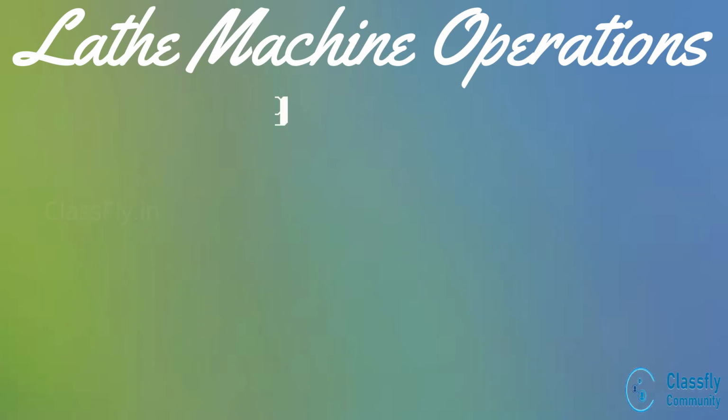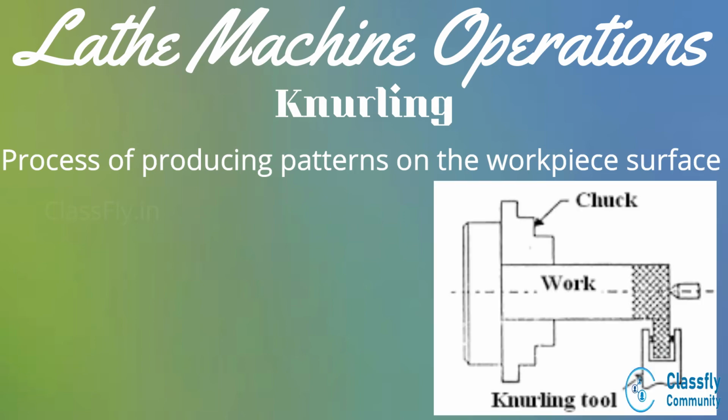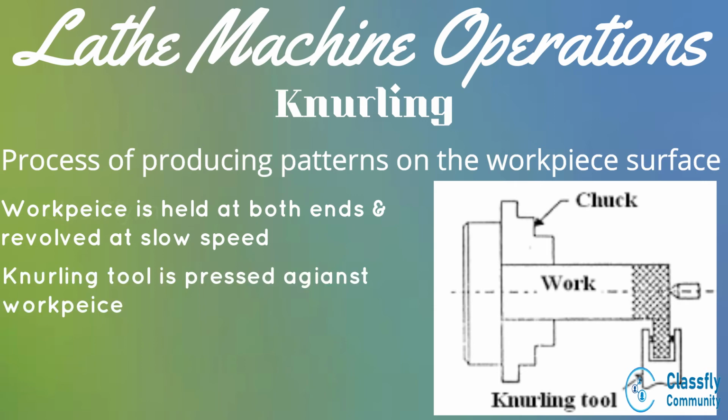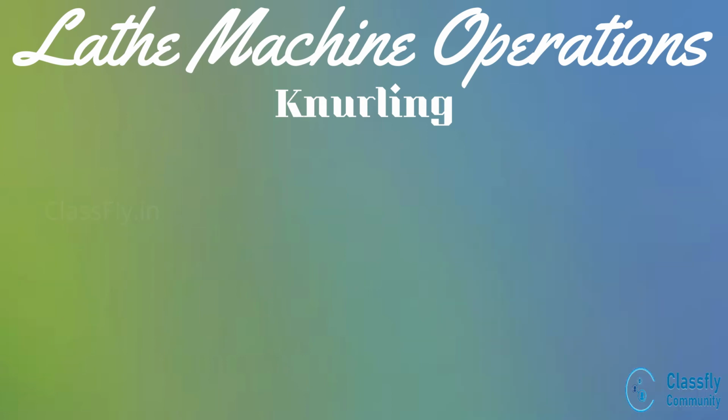Next, knurling. Well, knurling is a process which produces crisscross patterns on the surface of the metallic workpiece. In operation, the workpiece is made to revolve at a slow speed. The knurling tool having the required pattern is then pressed against the rotating workpiece. Hence, as the pressure increases, the tool will produce its pattern on the surface of the workpiece. By the process of knurling, a variety of knurled patterns can be produced. Some of them are shown below.